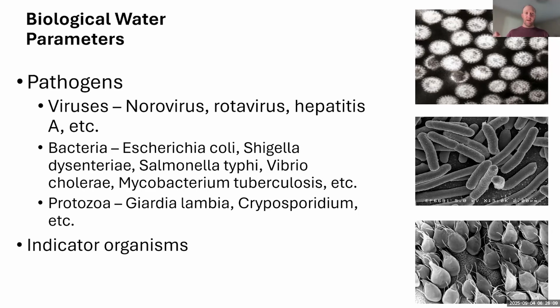So for drinking water systems, you have to take your bacteriological samples monthly, also called the BACTs, if you ever do those. And so you are testing for E. coli, but also you're just testing for total coliforms. And so these are more just used as an indicator to tell you, oh, there's a lot more bacteria in there. There could be pathogens, harmful to people's health.